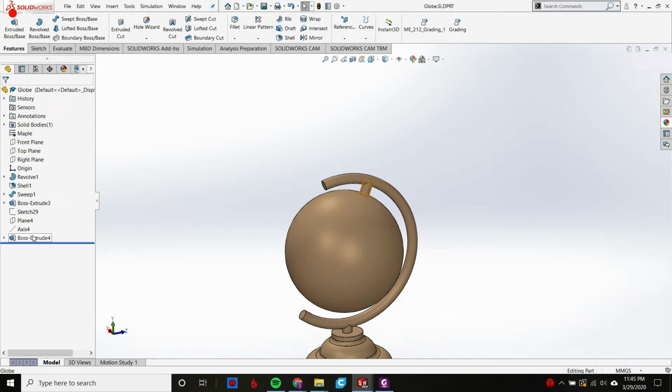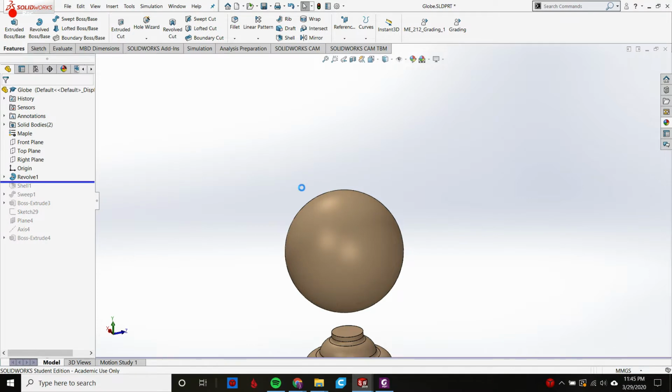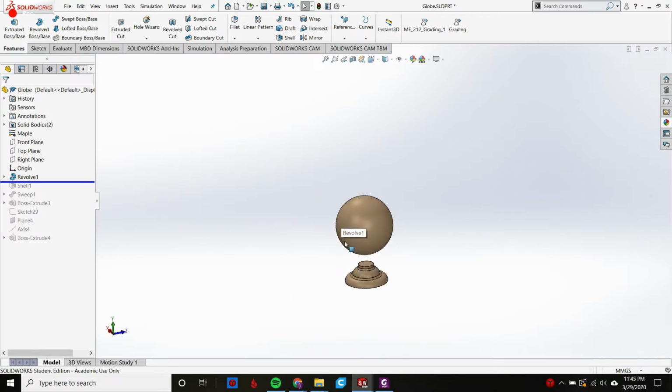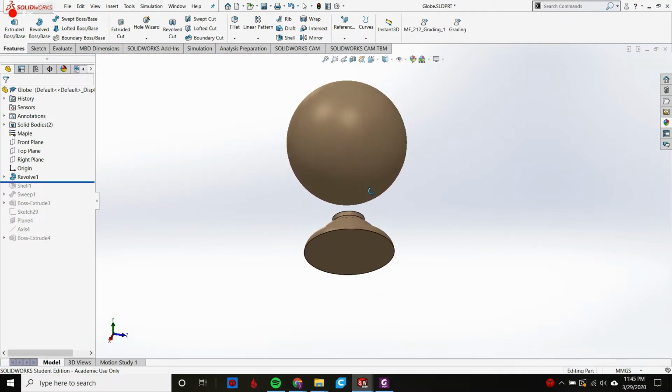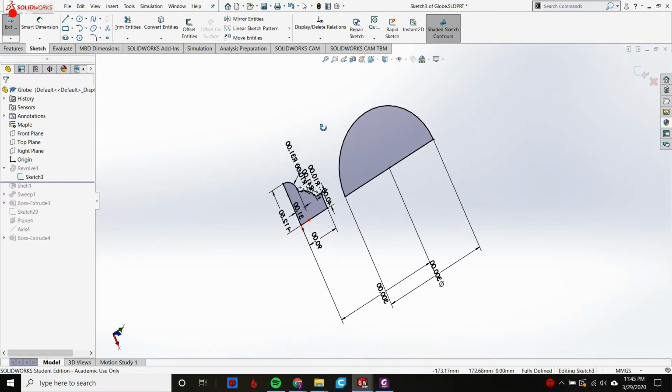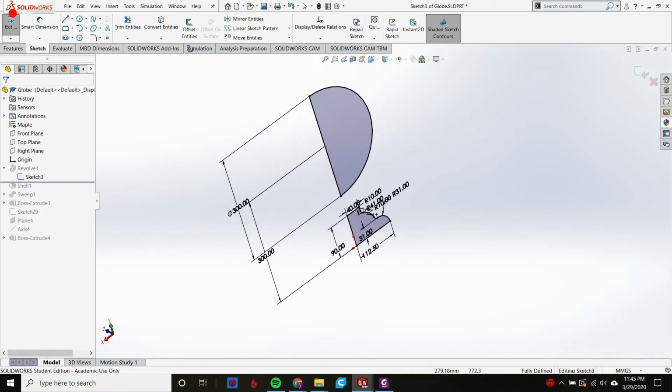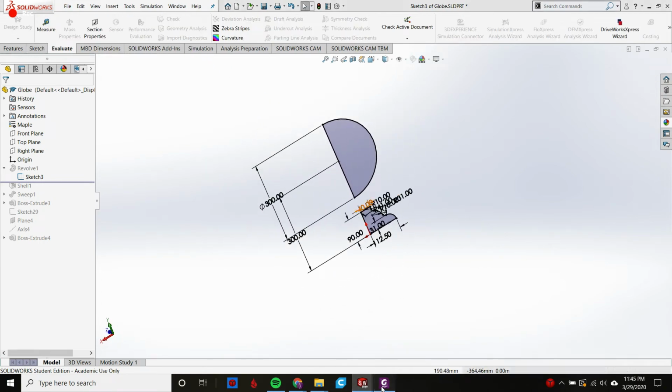If you're getting caught up, you might be watching this video hoping for me to explain a little bit, which is exactly what I'm going to do. So first we did a revolve. You might think, oh, I'll just do the bottom first. But you can do the revolve and you can do both these pieces in the revolve. So if we take a look here, we can do both these sketches, right? And then we don't have to revolve that circle later because we're given all the dimensions we want for it.